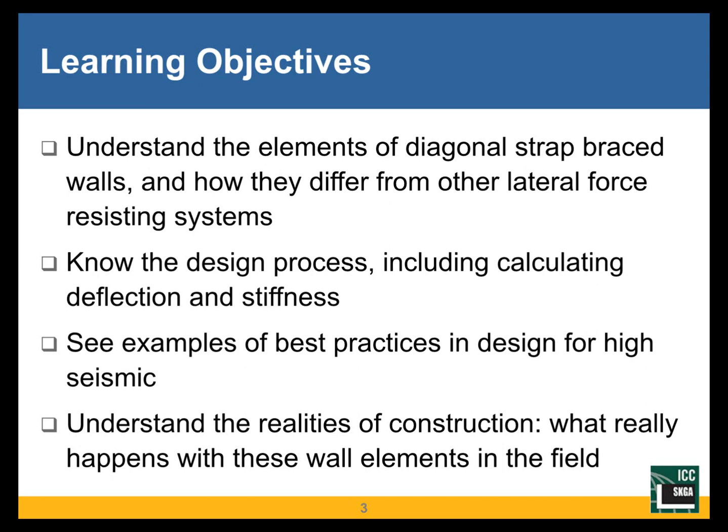Now, a strap brace shear wall may not necessarily be in a load bearing wall, but it is structural in nature. It is part of the structural load resisting system, and therefore it has to be made from structural materials. And we'll get into that a little bit more. But in cold form steel framing, there is a difference between structural and non-structural, and that's a very important demarcation.